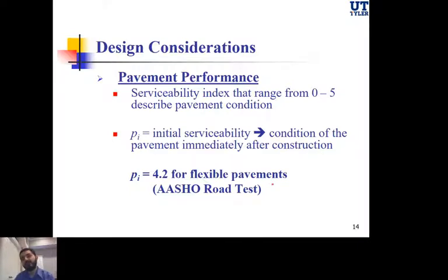Another design consideration that we're going to use in the nomographs next lecture is the pavement performance. A pavement performance is designed and is quantified by what we call serviceability index. Serviceability index, it ranges as a scale, how good is the pavement, from 0 to 5. 5 is the best pavement performance, and 0, this is pure failure. And typically we don't wait till 0 actually, the lowest would be 2.